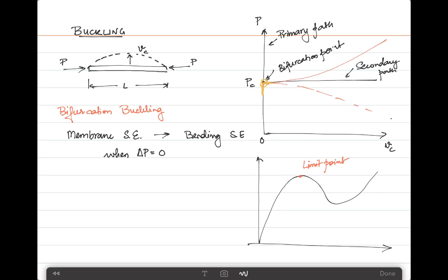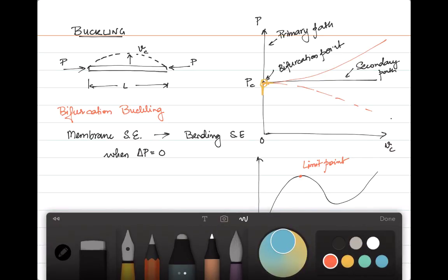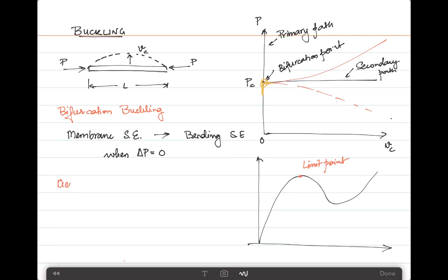Now, in finite element analysis, the effect of the membrane stresses on the lateral deflection of a structure is accounted for by means of a certain matrix that has already been introduced to you in the previous week. This particular matrix is called the geometric stiffness matrix. It is also sometimes referred to as the stress stiffening matrix. In the previous videos, it was referred to as matrix Kg.